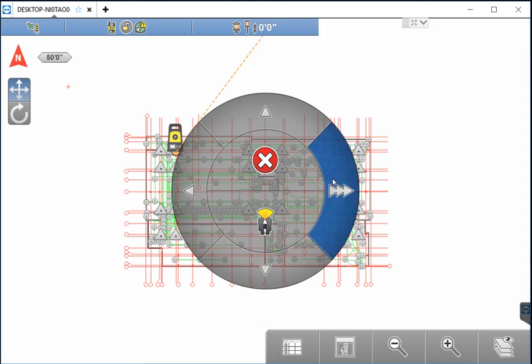The upper middle button above the binoculars is a target search area. It causes the total station to search a very small sector, and if it finds the prism, it will auto-lock. This is especially useful when you know you are pointed close to a prism. Touching the binoculars returns you to the previous options. Let's go there.